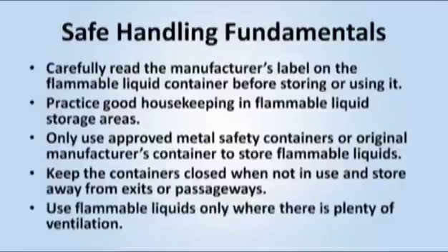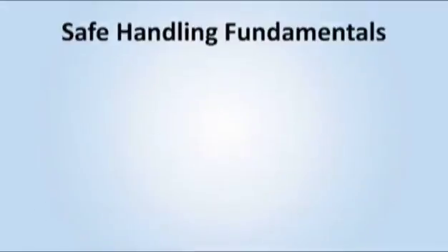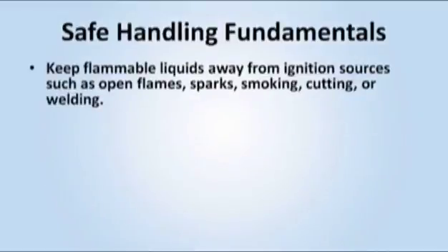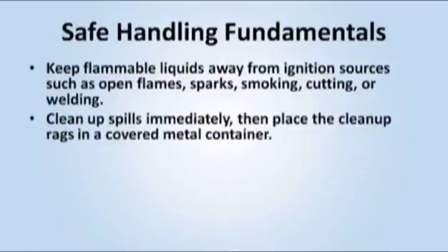Use flammable liquids only where there is plenty of ventilation. Keep flammable liquids away from ignition sources, such as open flames, sparks, smoking, cutting, or welding. Clean up spills immediately, then place the cleanup rags in a covered metal container.